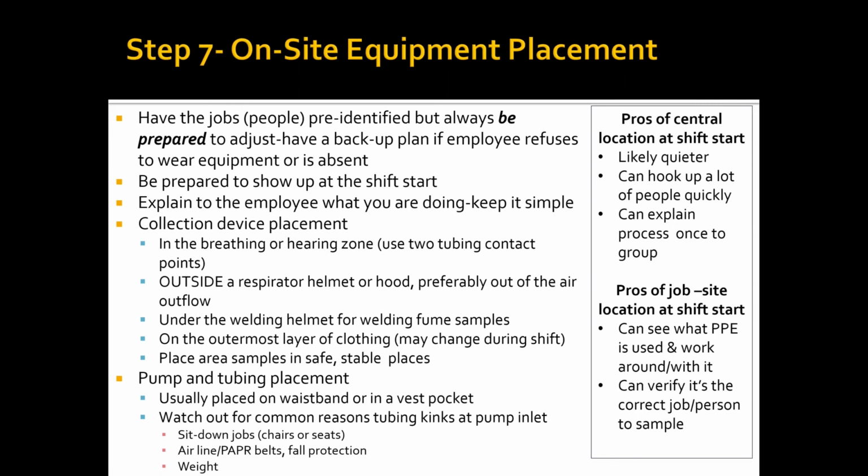I always explain to the employee what I'm doing. I try to keep it as simple as possible. It's not a chemistry experiment. I'm just telling you, here's what you have to do if you have problems with a contact, that sort of thing. A couple of highlights I want to hit here are on collection device placement. It goes obviously in the breathing zone, so you want that sampling device up close to the person's head, or in the case of noise, up in the hearing zone.